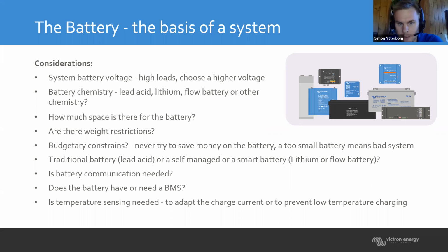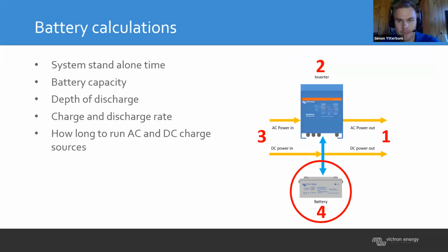As far as the budget comes into selecting the right battery, buying too small of a battery will cost you more money than what you're saving on the initial purchase of it, because a battery that's too small will work much harder and therefore fail much earlier, and now you have to spend another round of money for batteries. So yeah, try to get the battery to at least a 24-hour rate that we're gonna cover here.